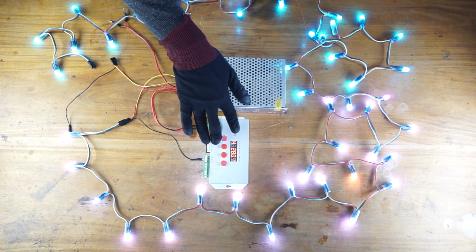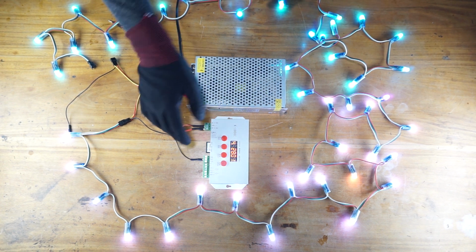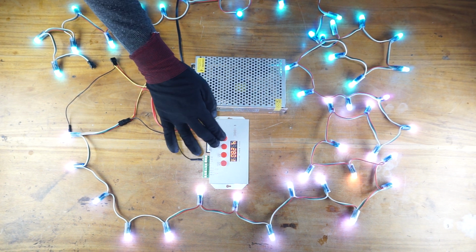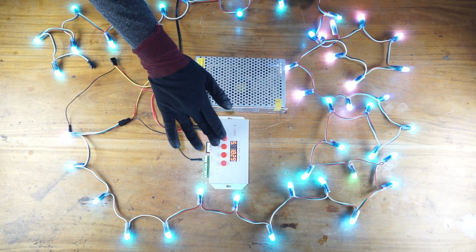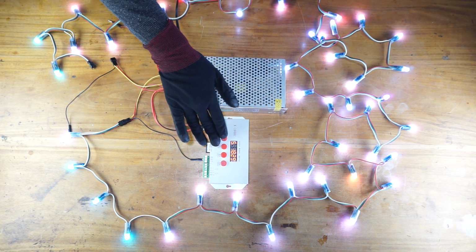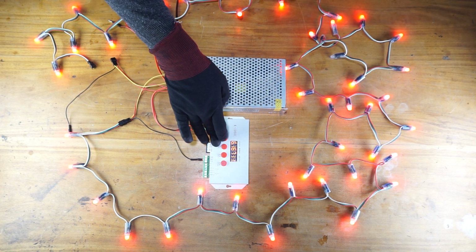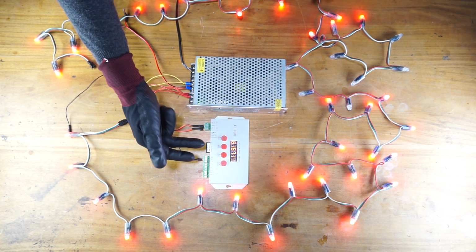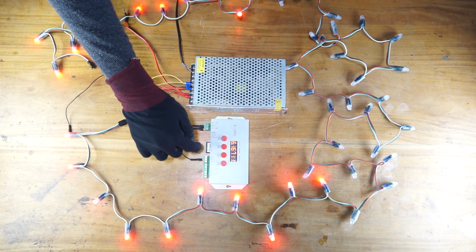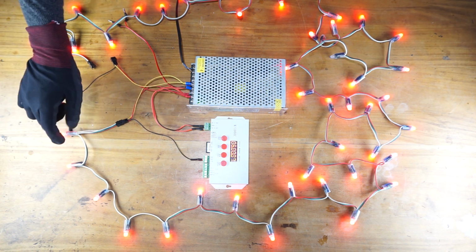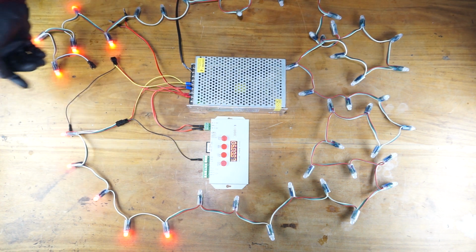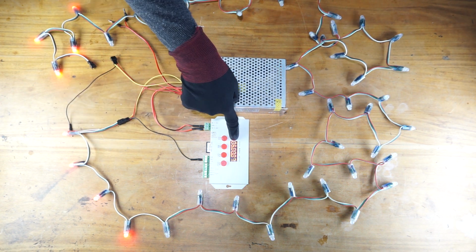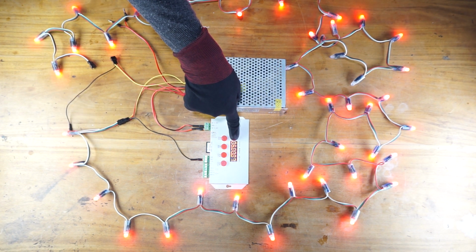In the 4th group, there is still no playback of the effect inside the SD card. I'm going to the 5th group. As you can see, it's still not the pattern we want. I'm going to the 6th group. Alright, now you can see the pattern. This is the correct pattern of the effect file inside this SD card playing on this pixel LED string. So for WS2811, the correct chip group is 6.